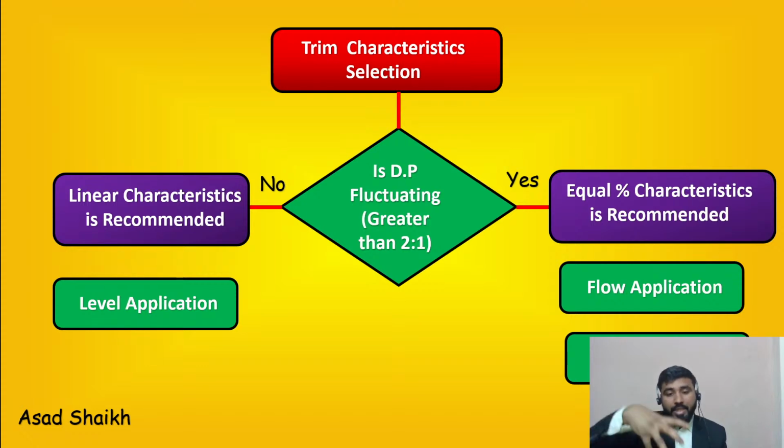And if you have a cage guided valve, you can remove one cage and put another cage also. Still not recommended. First thing is to design the right valve from the initial position. Better is not to make any changes at site, is what I personally prefer.